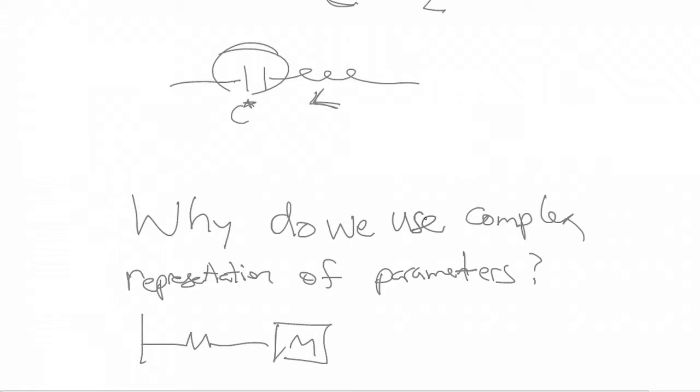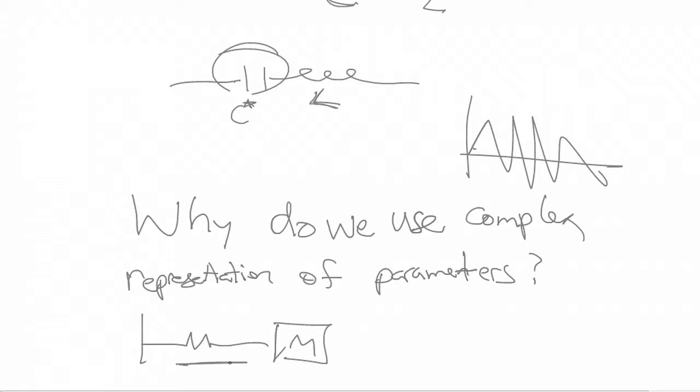You're moving back and forth, and sometimes the elastic energy is maximum, sometimes the kinetic energy is maximum. But it's really the change in energy happening within the spring which is causing the losses, not the fact that you're getting kinetic energy. That is not included in the losses.